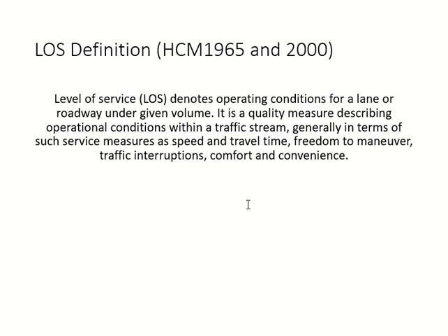So what is included in level of service? We have, for example, speed and travel time. When speed is higher, that means the level of service is good, the traffic condition is good, so it's more towards A. By the way, level of service goes from A to F. A is free flow, F is when demand exceeds capacity. Travel time has an inverse relationship: when travel time decreases, level of service becomes good, towards A.